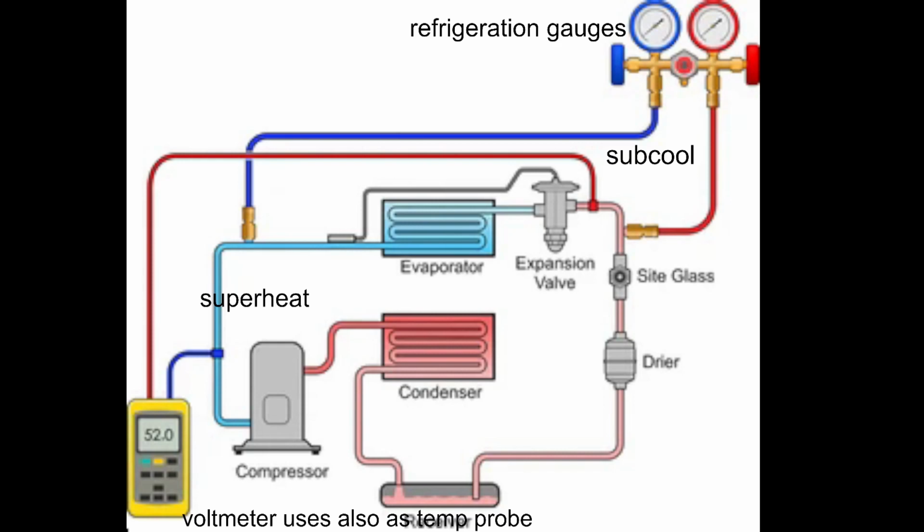The other one, and I only put those in on systems that are basically designed to reverse themselves. They have reversing valves in them. And that's where I use the sight glass. You can put a sight glass in it so you can see that your refrigerant flows on the high side. So basically, I put sight glasses on heat pumps, and we'll go over that one. Heat pumps, a different dinosaur altogether. It still runs in the same format, but it does something different in a way.